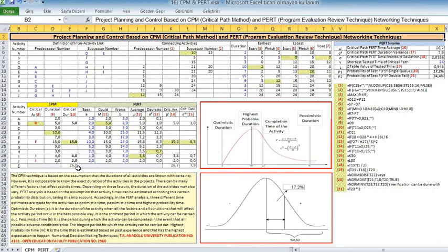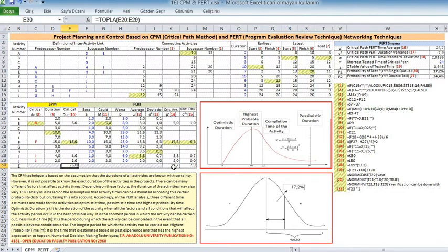2. PERT is a technique of planning and control of time, unlike CPM, which is a method to control costs and time. 3. While PERT evolved as a research and development project, CPM evolved as a construction project. 4. PERT is set according to events while CPM is aligned towards activities. 5. A deterministic model is used in CPM. Conversely, PERT uses a probabilistic model. 6. There are 3 time estimates in PERT, i.e. optimistic time, most likely time, and pessimistic time. On the other hand, there is only one estimate in CPM.